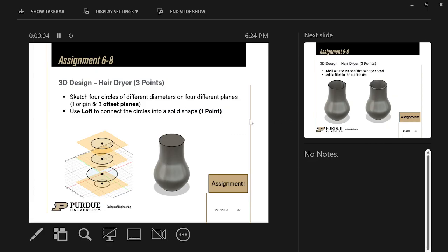To start off with the body of the hairdryer, I'll open it back up again. I'm going to explain what we're doing first. To get this kind of weird, non-symmetric, inorganic shape, we're going to make various sets of circles at various heights, and then we're going to do something called a loft. We're going to collect the boundary, right? You notice that each of these circles has a boundary. That's the circumference. We're going to get each of the boundaries and connect them.